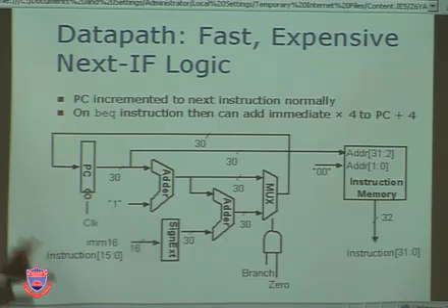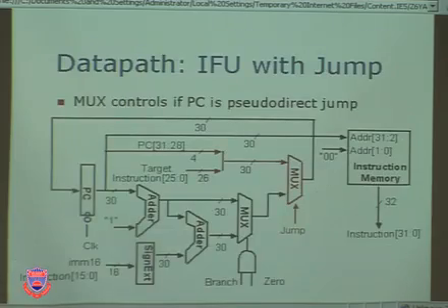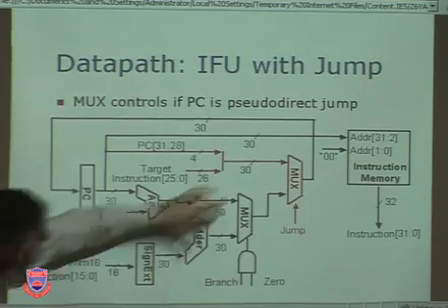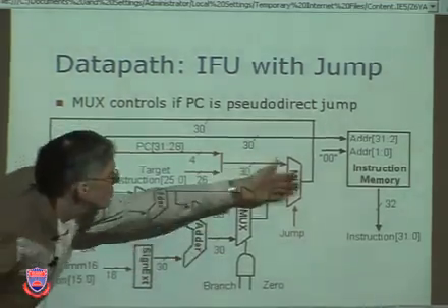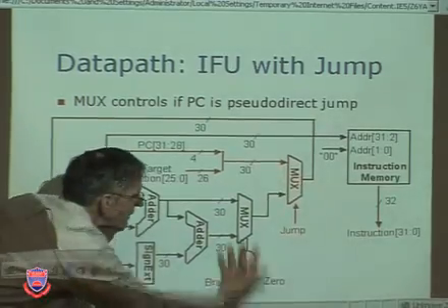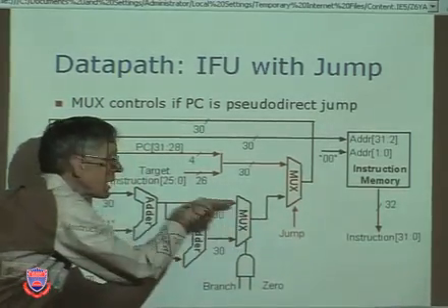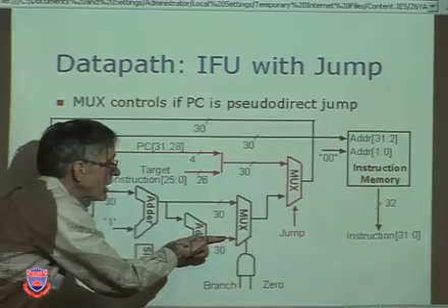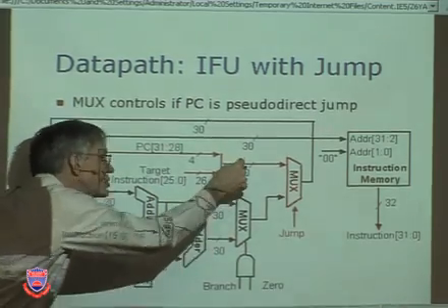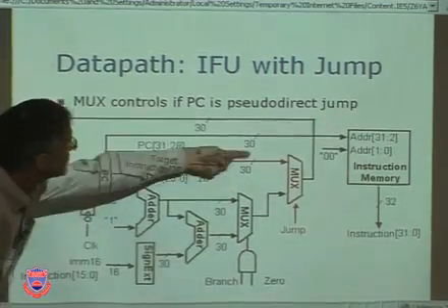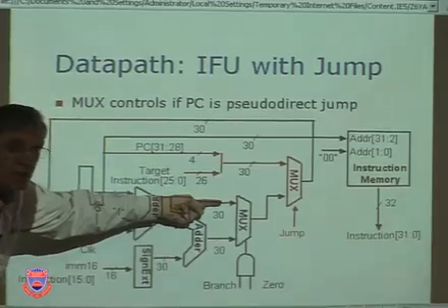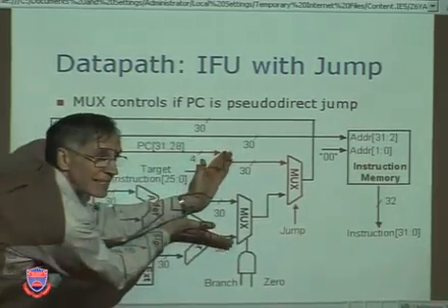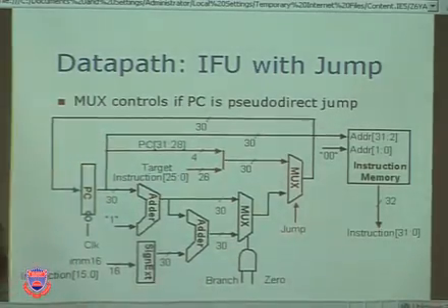If you'd like, we can move on to jumping. And watch close. See that model? We're going to just add one new red thing. Do you see now it's a single mux with 2 inputs. Let's go to jumping. Now it's 2 muxes with a grand total of 3 inputs. The new stuff is the red. All I did was keep that the same, and what was the choice before between sequential and branch address now becomes the choice between jump, sequential, and branch address. So there's the jump address, there's the sequential address, and there's the branch address. I got 3 choices. I do it with 2 muxes.